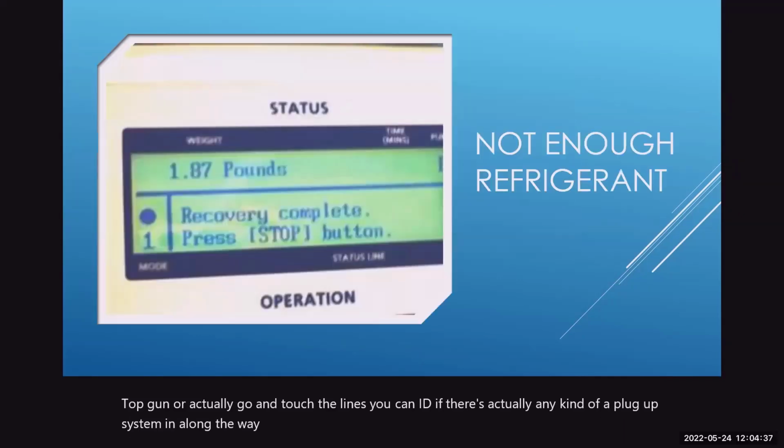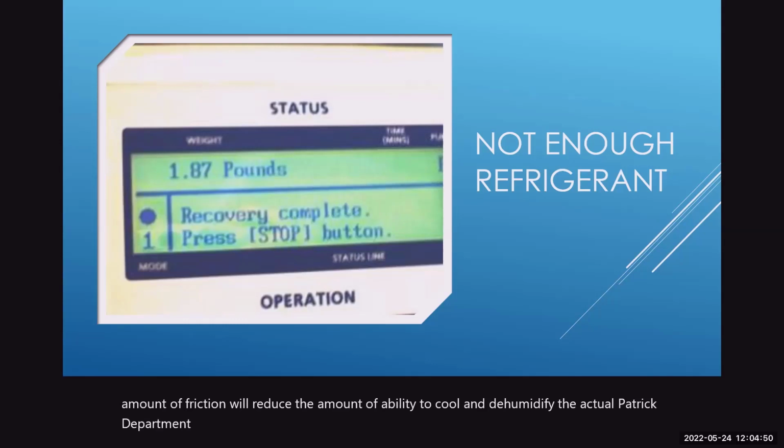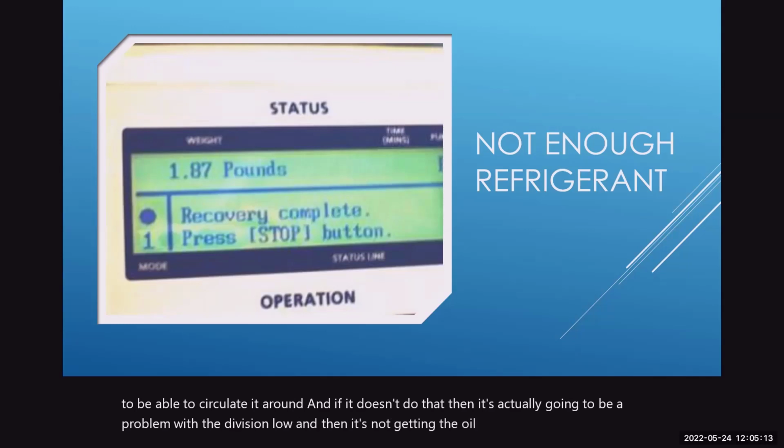So not enough refrigerant could be a problem. Any loss in the amount of refrigerant will reduce the ability to cool and dehumidify the compartment. The reduced charge also affects how the oil gets transported. It gets transported through the refrigerant, so we need to be able to circulate it around. If the refrigerant is low, it's not getting the oil around to where it needs to go.